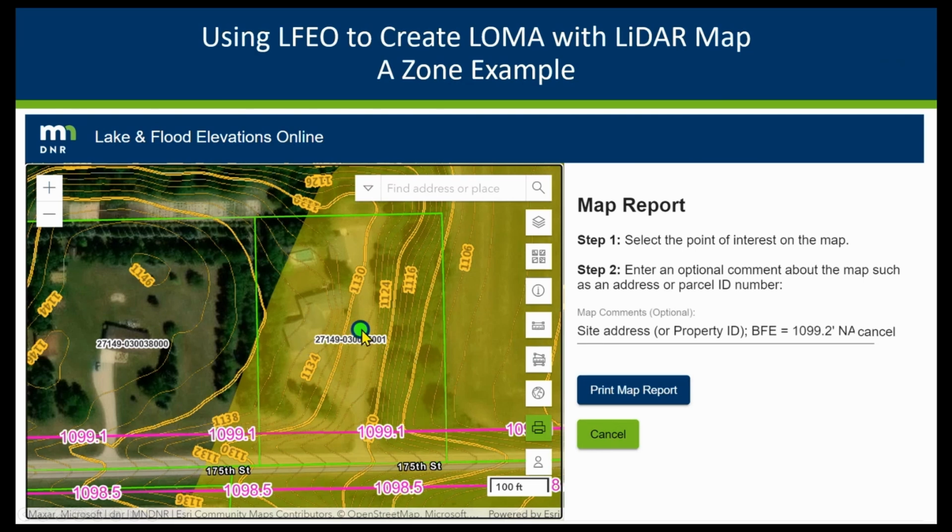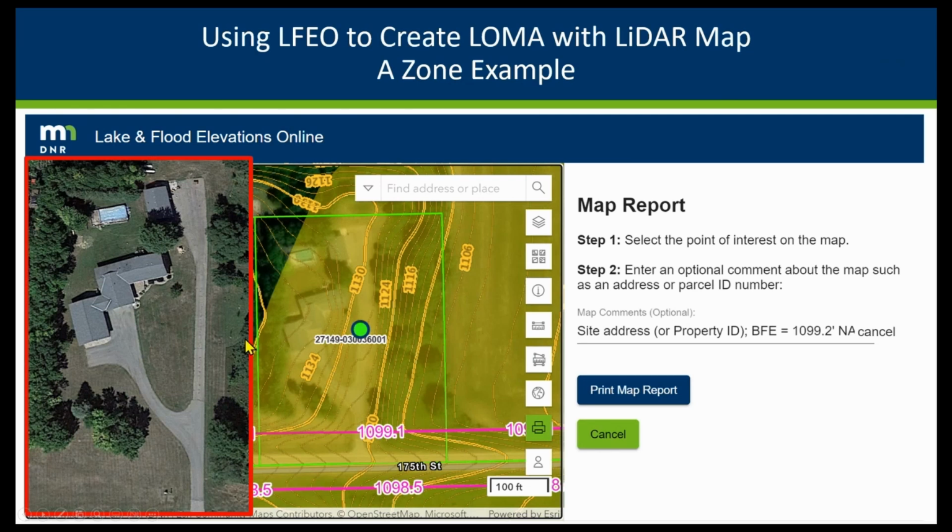And I've already done the location information, and I'm looking here at where is the edge of that property. It's a little tough to tell. So I've done some looking at an aerial photo, and I might look at better aerial photos on the local county site or community site and be able to see an overlay with the 2-foot contours. But I determined that the edge of the building is just below this 1130 contour, and that the 1128 contour is below the building. So I've entered additional comments in the comment section about the lowest adjacent grade.